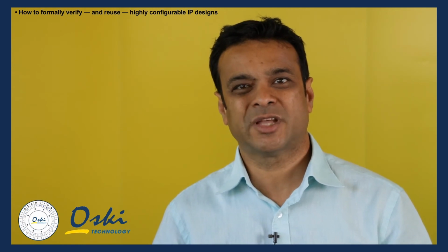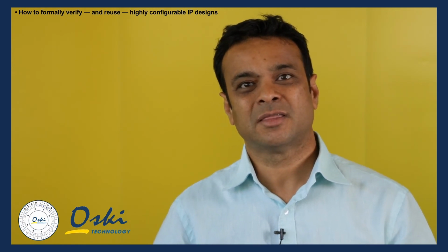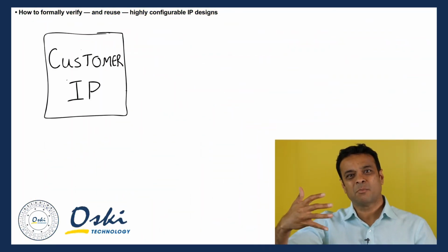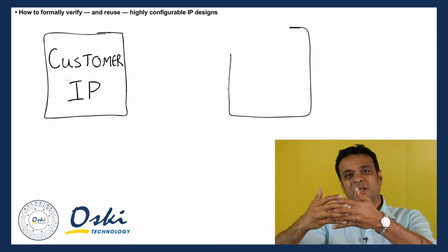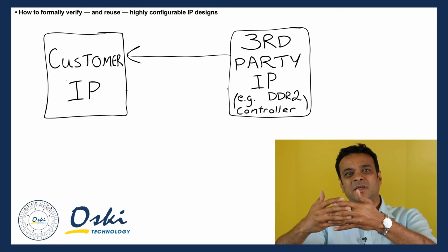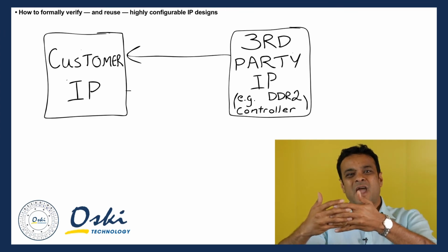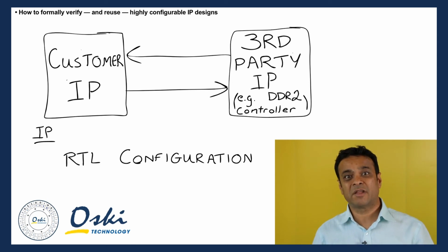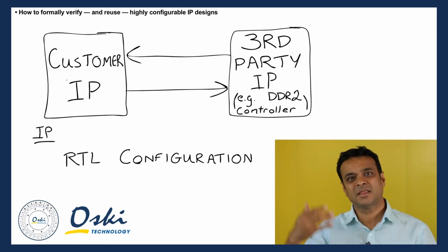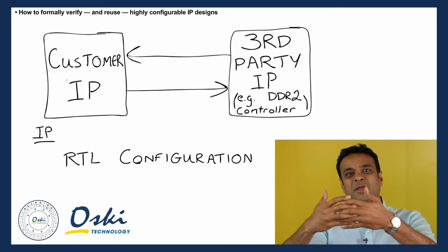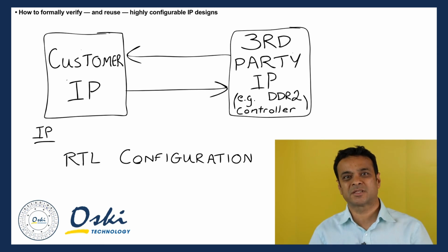Moreover, the properties that you get in this configured test bench are used to verify the IP vendor's design IP, but you can also use the same properties to verify your own IP, the customer IP that's integrating with the vendor IP and working together, because you want to be sure that all possible corner cases that were verified and designed in the vendor IP have been verified with your own customer IP, and together they work seamlessly and you have no corner cases to worry about.